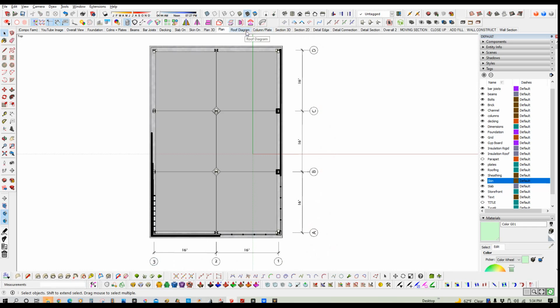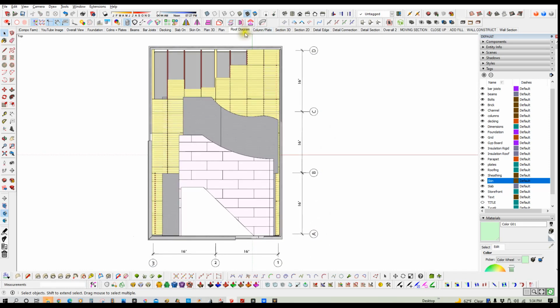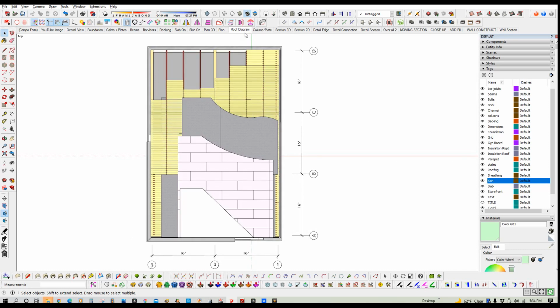Roof diagram. Now, what does that mean? I put together a layering effect for the roof so it shows you the different components, if you will. Starts with the steel beams, bar joist, the floor decking or roof decking, metal deck, concrete slab, tapered insulation, EPDM roofing membrane. So what I'm looking at is that I could take this and just go to text here, which